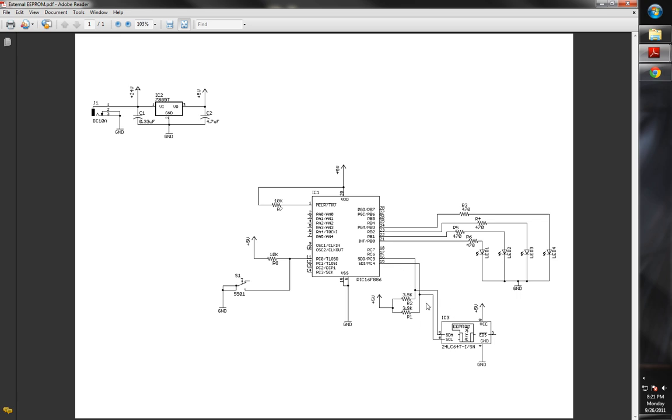But for us, we're going to do something really simple. We've got 4 LEDs and a switch, with a pull-up resistor and our switch for pulling it to a low. So we're using inverse logic. It's going to be 1 all the time, and then we'll be waiting to see the 0 when you push the button.